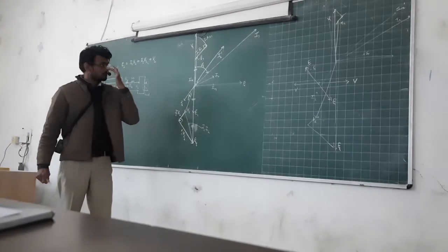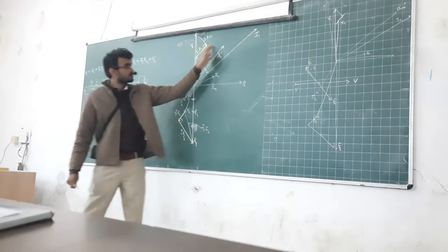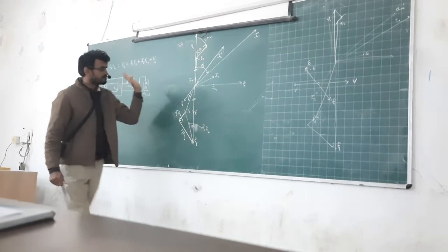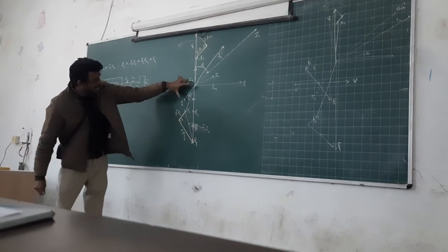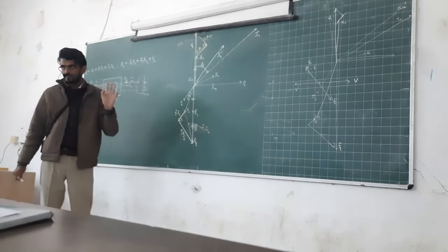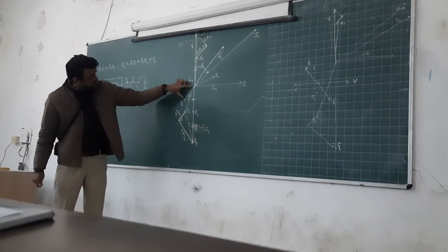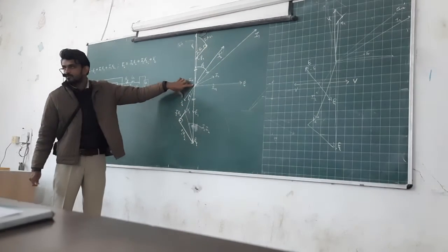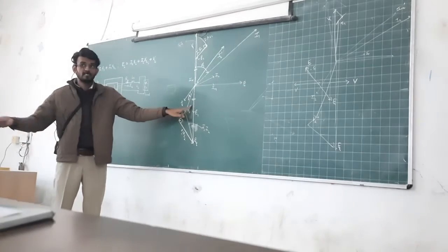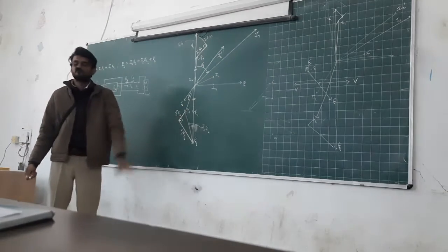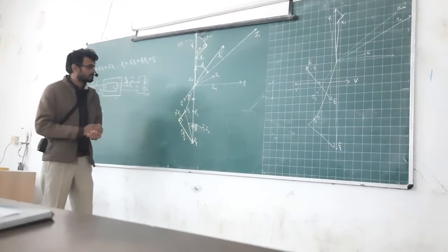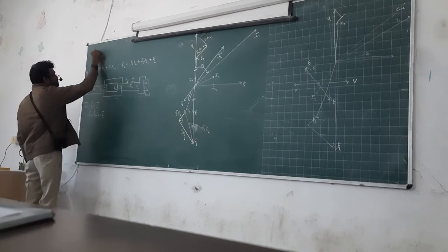Okay. So in your syllabus, only half of the portion of the phasor diagram is considered, but we cover the complete portion. So previous was resistive. For that, I2 will be in phase with V2, and then you have to follow all the steps. Then if RL comes, then I2 is lagging behind V2. If capacitive comes, then this I2 will go here because it is leading. So it will be leading here, and then you will have to follow the steps. Okay. Capacitive we are not going to discuss right now, but this is called the RL load. Okay. So here is the phasor diagram for the transformer on RL load.